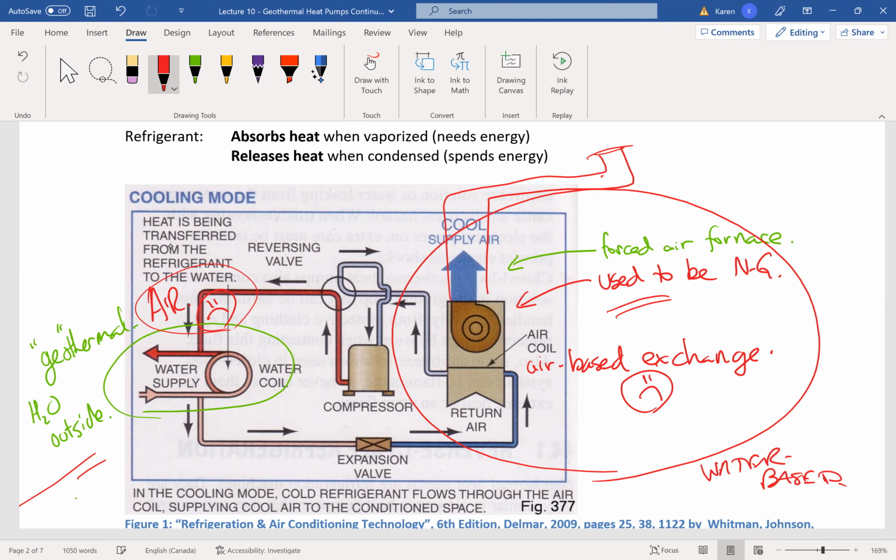But right now with retrofits, if you were to get a heat pump, this is what they would do, right? They just put it into your previous natural gas furnace setup, exactly. That's what they're doing, is putting it through this original ductwork. But then the system tends to be undersized on this side.